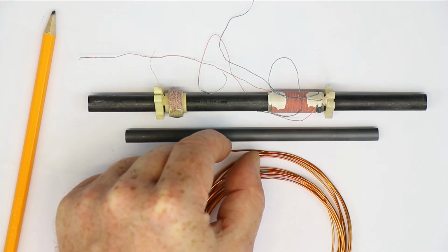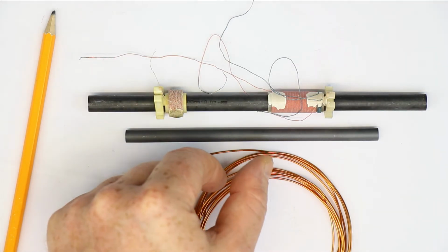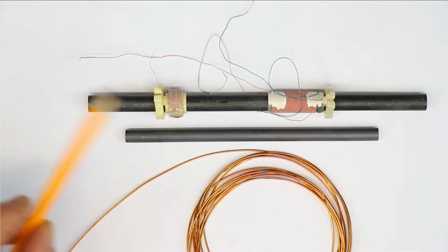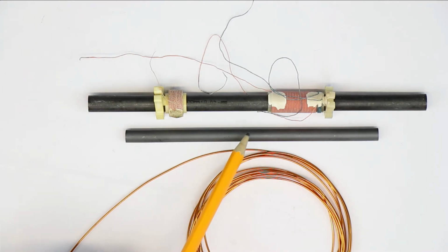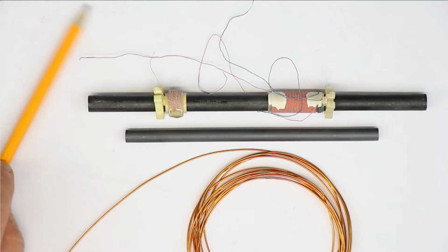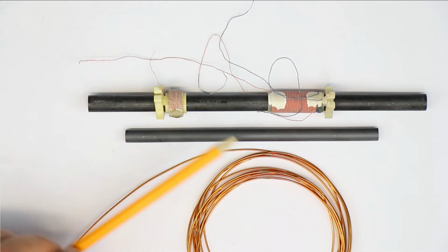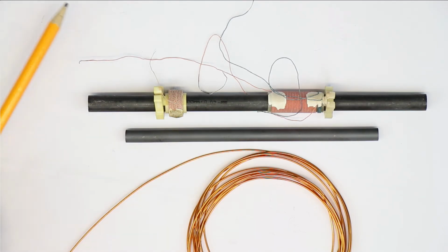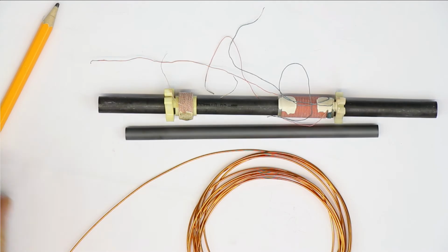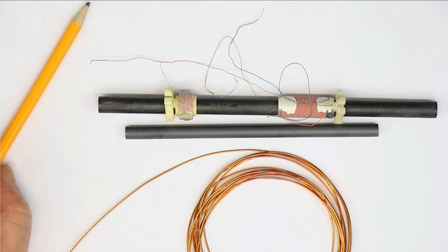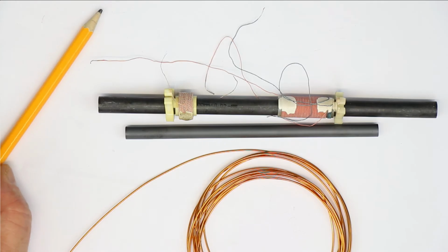The direction of the field changes from north-south to the other way around. And every change of the magnetic field, there's some energy loss, because reorientating the magnetic domains in this material just sucks up energy. And these are the magnetic losses. But every insulating material like cardboard or plastic also has losses, and these are electrical, or better said, dielectric losses.